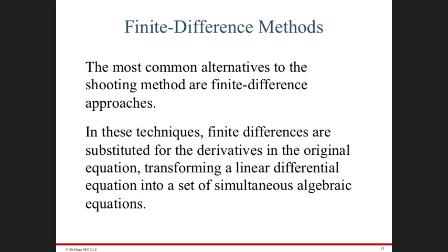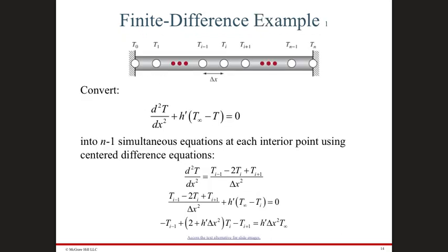So you go to the differential equation itself, and whenever you have derivatives, first order derivative, second order derivative, and so on, you represent those as finite differences, right? So you know how to do that, right? So for example, if you have this equation and you want to convert that into a finite difference equation, a second order derivative is typically represented by a difference between three values.